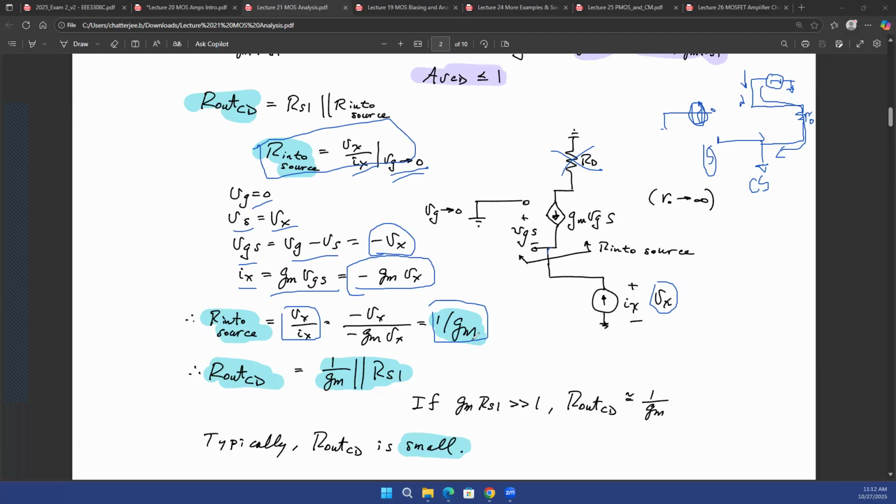So if you go to an interview in TI or Analog Devices, people might ask about what is the low impedance node in this circuit. So don't get confused. They're basically talking about the source terminal of the MOSFET in question, if they're talking about the low impedance node. And the high impedance node will be the drain terminal. Of course, the gate is also a high impedance node because gate has an insulator and it has infinite impedance because of that.